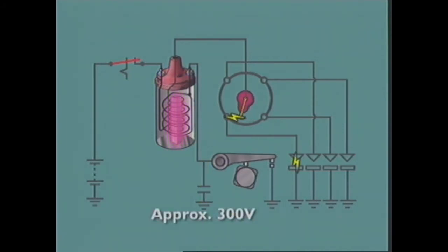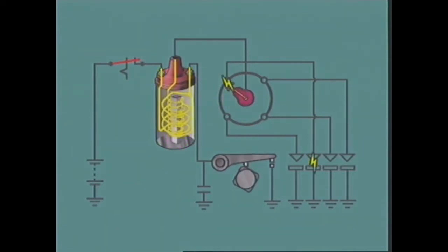The capacitor charges to the peak value of the primary winding voltage. By the time this has occurred, the gap between the contacts is too wide for a spark to discharge between them. This abrupt interruption of the primary circuit assists in the rapid collapse of the magnetic field, and hence an increase in the value of the voltage induced in the primary and secondary windings.